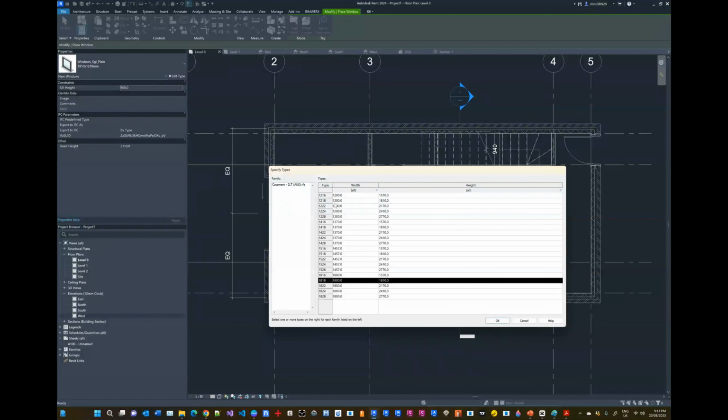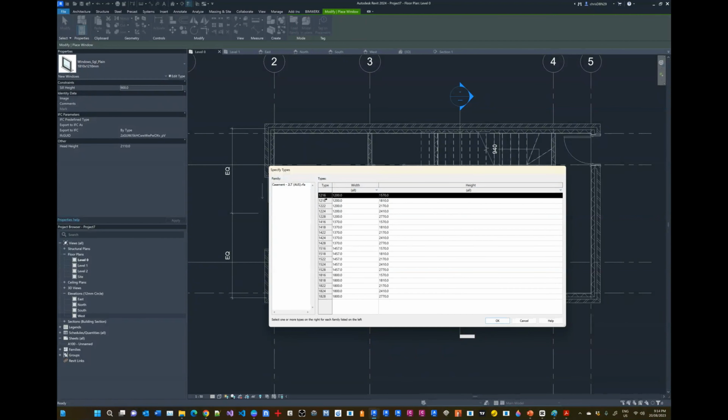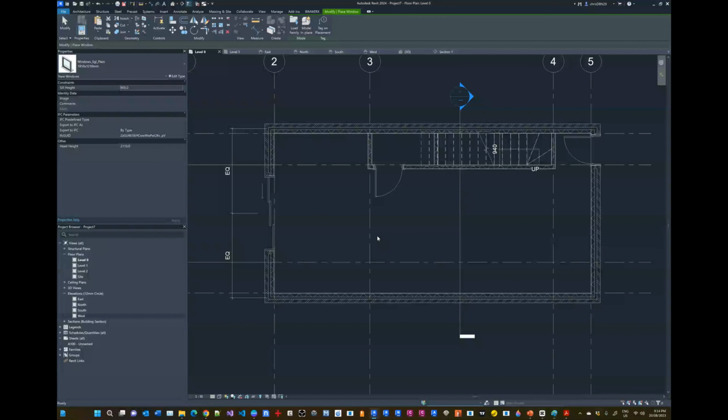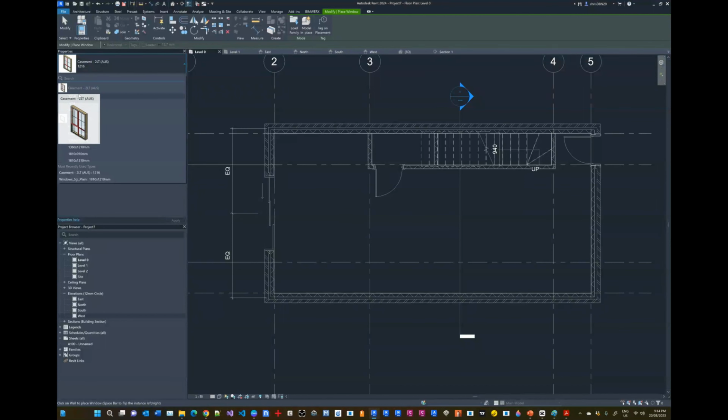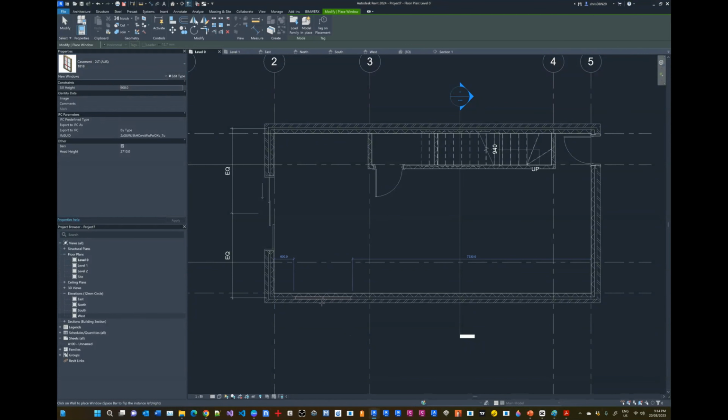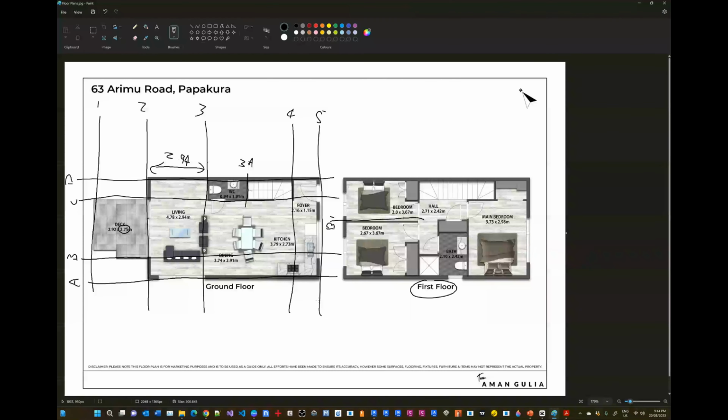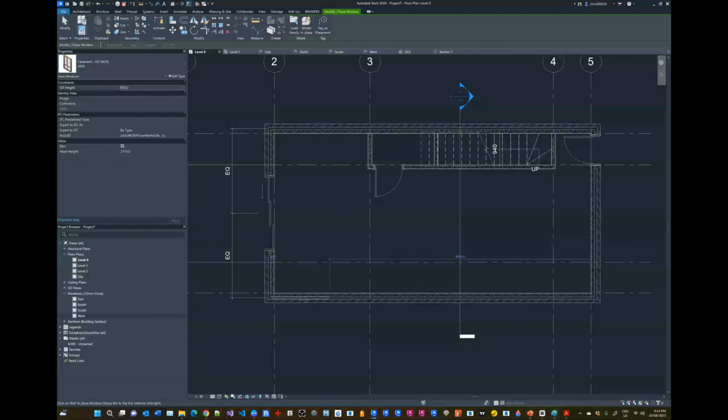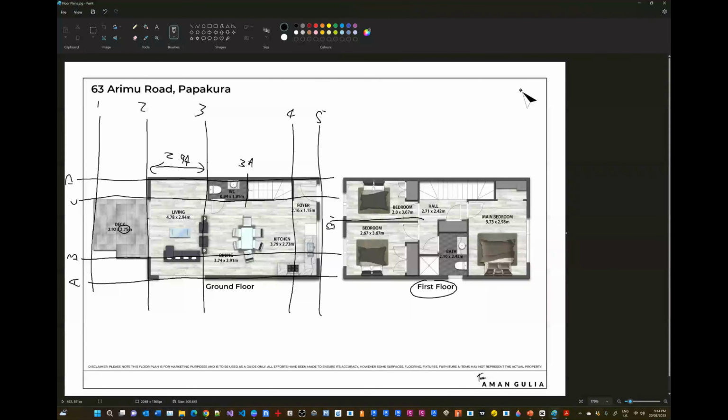And then for upstairs, for the smaller windows, we can probably bring in this one and this one. I'm holding the control button down to select multiple rows. And when I bring this in, you're going to notice immediately that it's going to, of course, change. And now from my drop-down list, from the casement one, I've got those 3 that I've imported. So I want this big boy over here. I'm going to select, where was that exactly? So that sits sort of here. I think that's good enough. Okay, so we've got that window there.